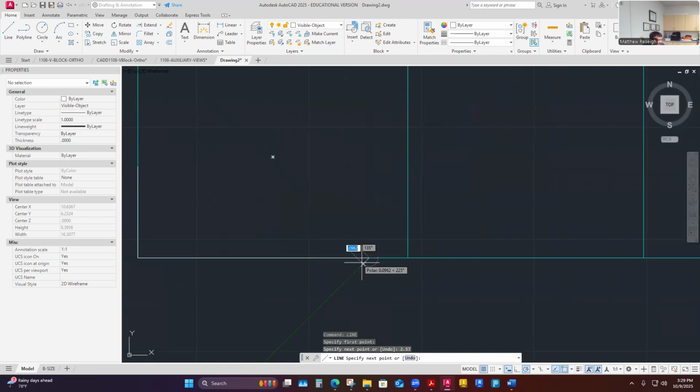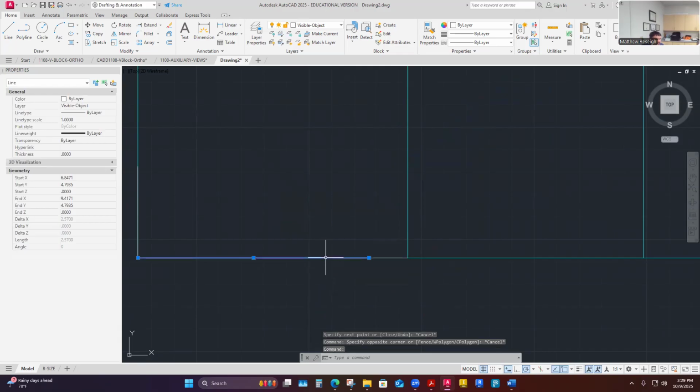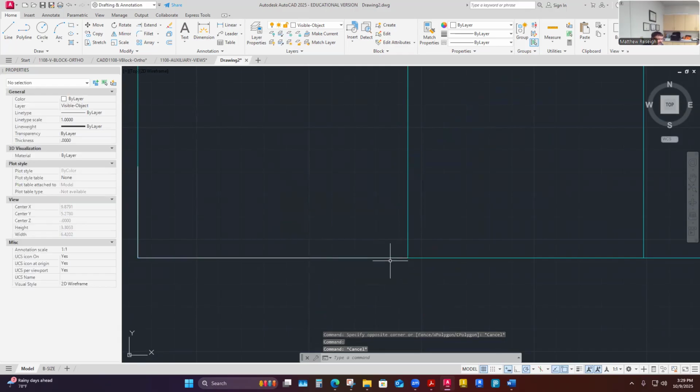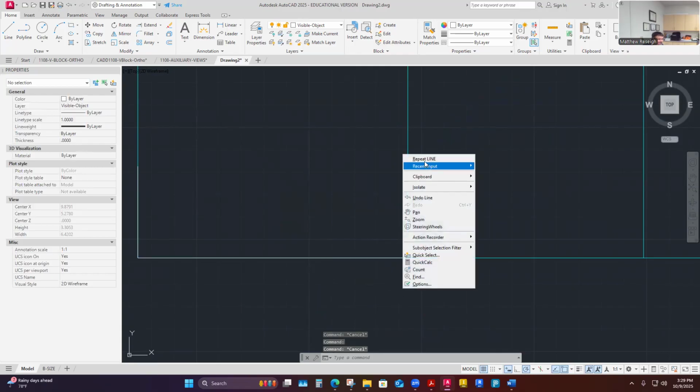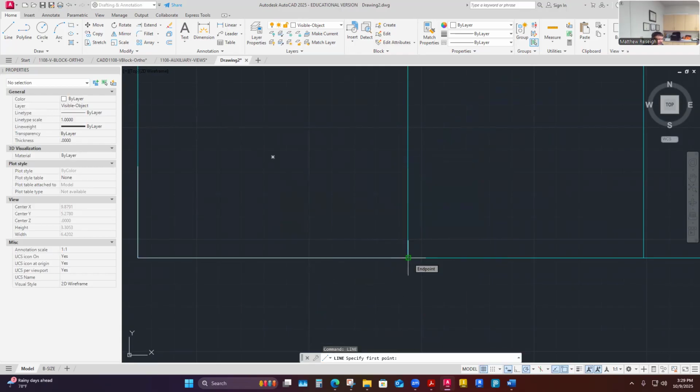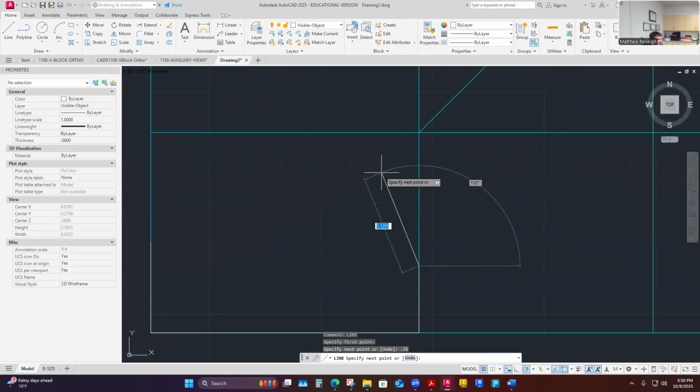And then it continues on, sloping away from me at this point back to the right side view. So I'm going to continue this line, but it's in two segments: a segment that's 2.57 and then a segment that's severely foreshortened over to the right side view. From the right side view, I pick up a dimension that's true length, and it's 0.75 up, right? Then I pick up an angular dimension on my print. It says it's 30 degrees from this point. It's going to slope over 30 degrees.